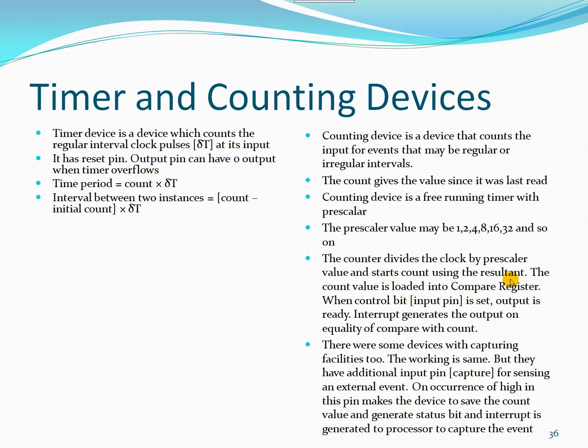For DSP processors also there will be a built-in dedicated timer and dedicated compare register for generating PWM pulses and for control clock pulses for the ADCs also.